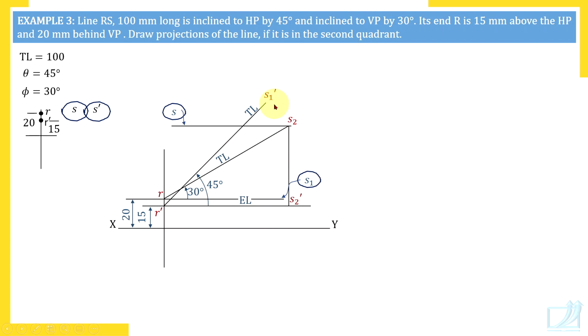Okay. Now through S1 dash horizontal line, which other point on this line? S dash. S dash and S1 dash always lie on a horizontal line. Do you remember? I asked you to remember that B dash and B1 dash lie on a horizontal line. Instead of letter B, letter S is used here. Is there any other point on which S dash is? No. So that is why by drawing horizontal line, you will not get S dash directly. So just label this line in this manner. That will remind you during construction that on this line somewhere S dash is.